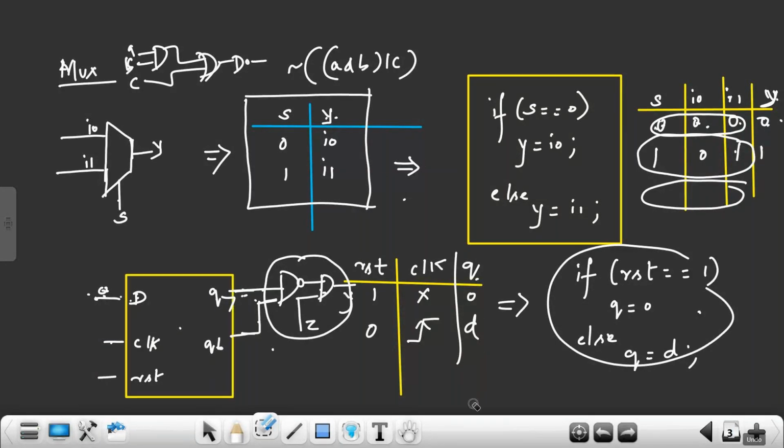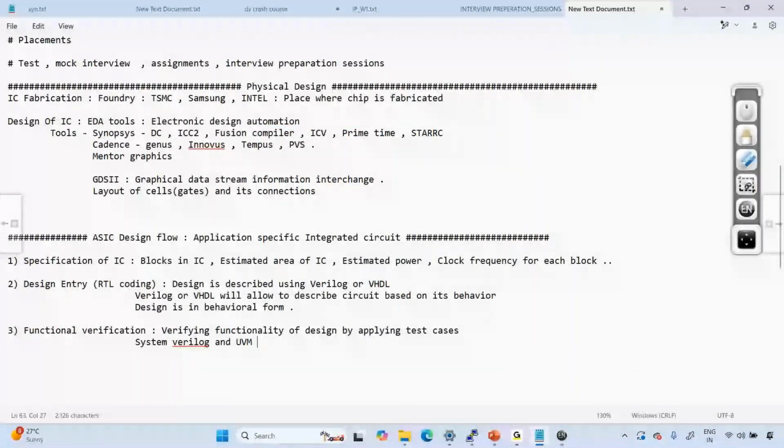Okay, I got it. I thought the functional verification also checks minimal timing, but it looks like that only happens at the synthesis level. Timing means there should be a cell delay, correct? The design is not yet at the gate level. Gate level happens only during the synthesis stage.